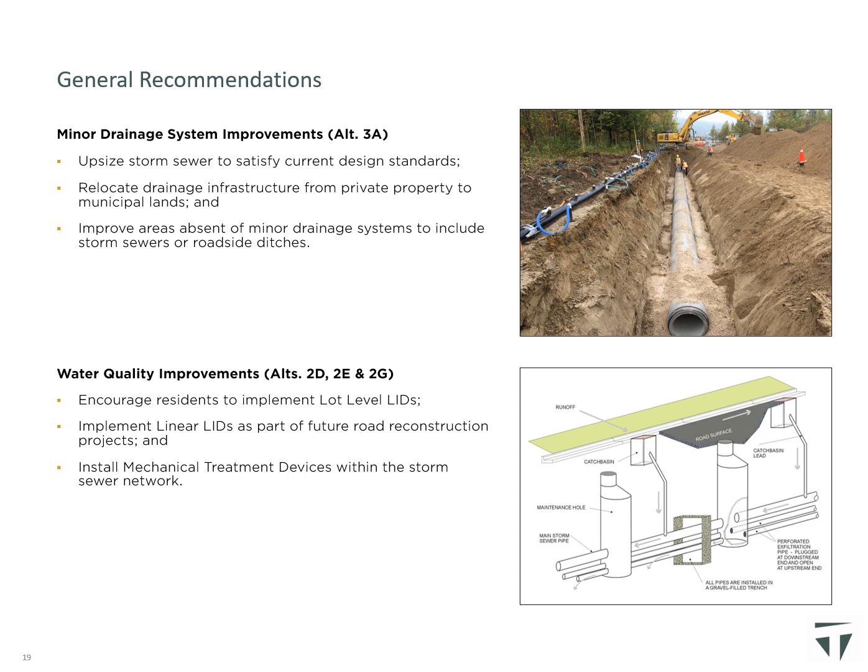Minor drainage system improvements under Alternative 3A, including upsizing storm sewer to satisfy current design standards, relocating drainage infrastructure from private property to municipal lands, and improving areas currently absent of minor drainage systems to include storm sewers or roadside ditches as part of future road reconstruction projects.